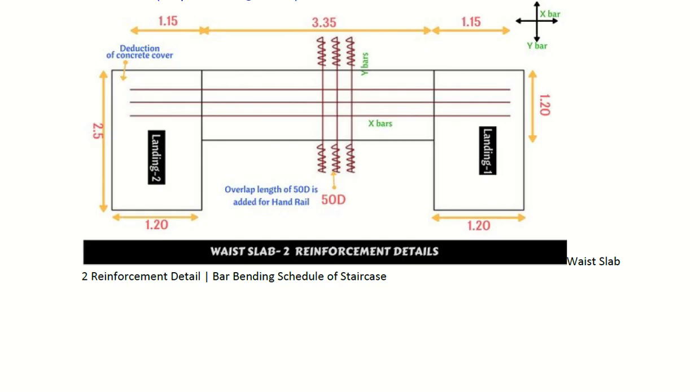Now for the landing, the reinforcement from the base slab is going into the landing, right? So in the X direction, you already have the reinforcement coming from the base slab. This one is going in, right? So I don't need any other reinforcement in this part of the slab. I will need one in the Y direction, right? For both landing slabs, I need the reinforcement in the Y direction. Clear or not?